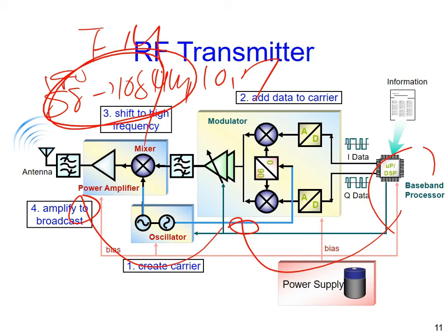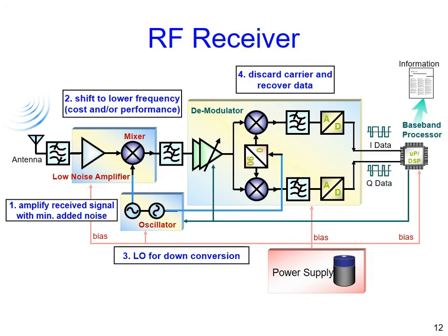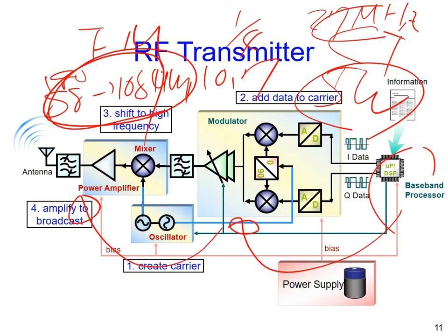When I was young, I lived at the top of second dormitory. When I was single, I played some kind of city band, with only 5 watts. But how about the antenna? I just got some kind of wire. Then I cut it according to maybe 1/4 wavelength because the frequency is around 27 megahertz.